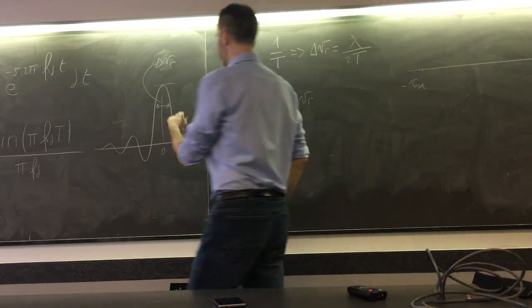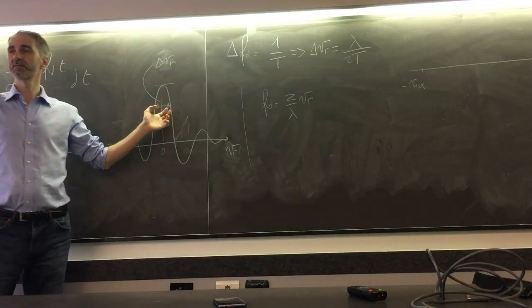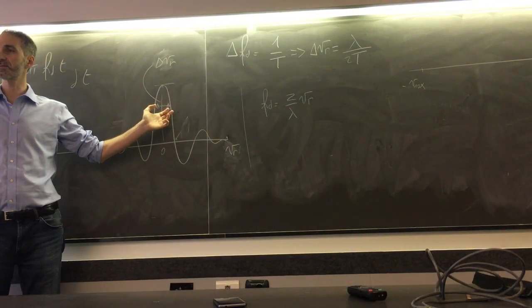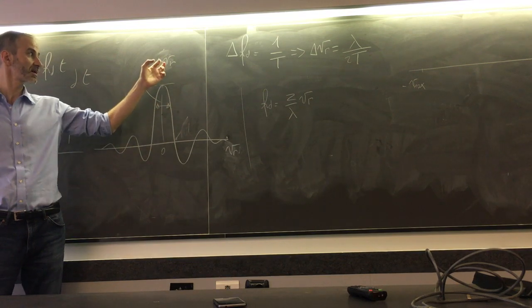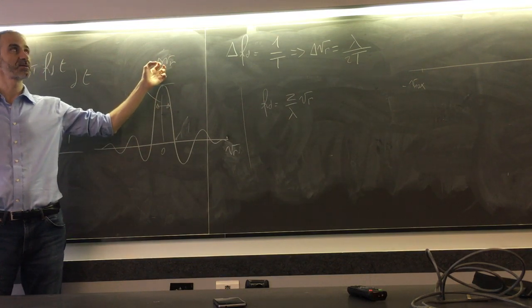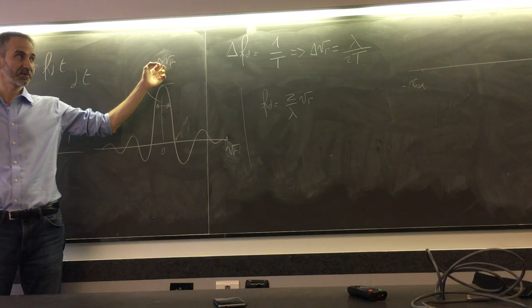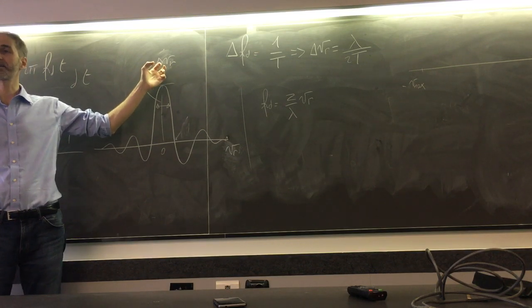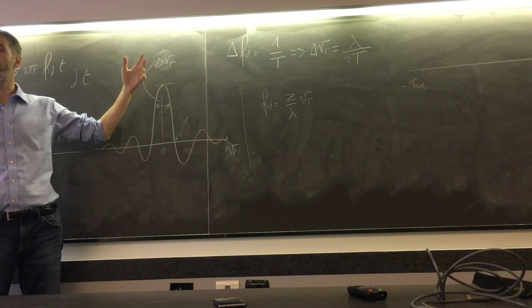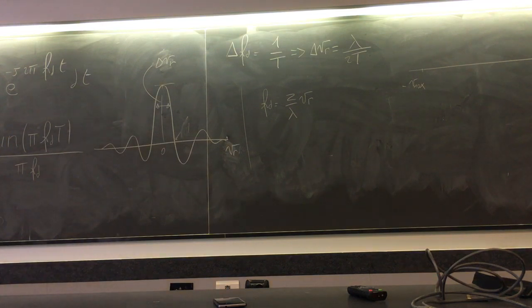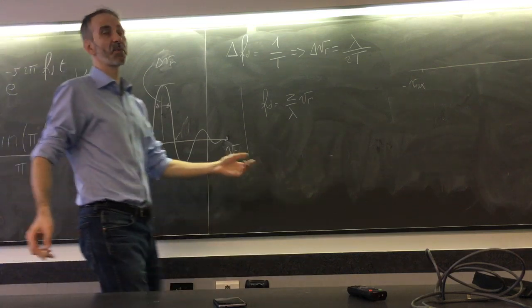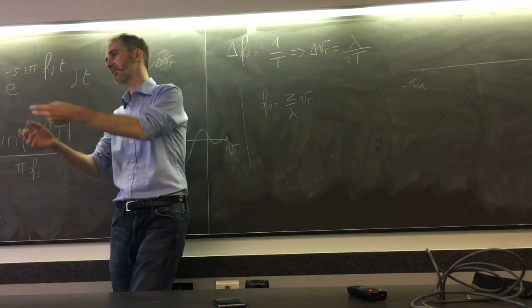You know that you are capable of resolving targets as long as the difference of their velocities is larger than this value. So how many Doppler frequencies do you need to test? The max minus the min, divided by the resolution. With some margin, if you like, you can assume a factor 2.